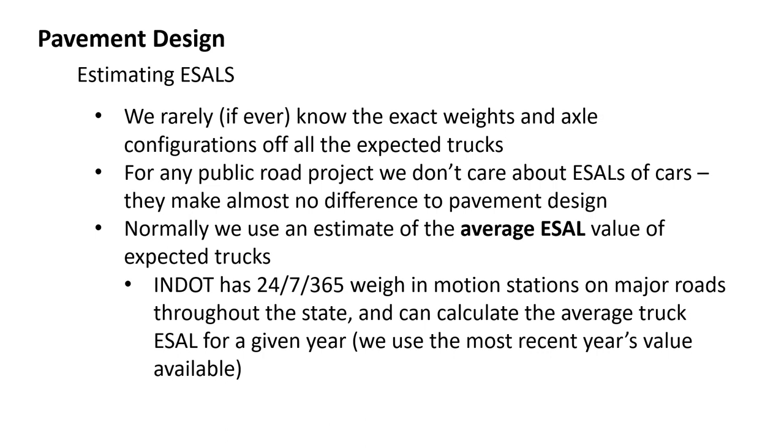The way NDOT does this is they've got weigh-in-motion stations out on mostly interstates, but also some major state highways, and typically truck routes. That's where they like to put these, because that's where they care more about how much trucks weigh. They monitor those all year round and calibrate them off and on as they need to. From that data, they can tell you pretty exactly what the average ESAL value of a single truck is and what a normal truck is on Indiana's roads.